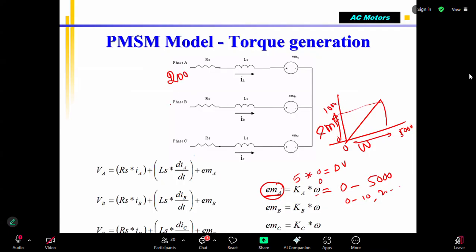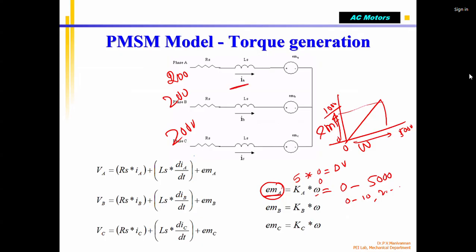Applying, say, for example, 200 volts for an AC voltage with peak value. Back EMF. We know that already I told you the current IA, correct? Current IA is nothing but supply voltage, that is V voltage minus back EMF voltage divided by Z. That is what IA is. In AC motors, the voltage applied minus the induced back EMF, or AC or DC motor. Motors, it happens wherever the back EMF is generated. Supply voltage minus back EMF divided by Z will be the current flowing at any given time.